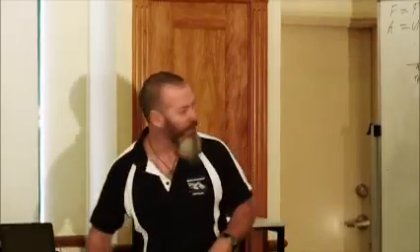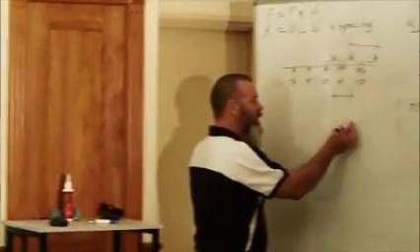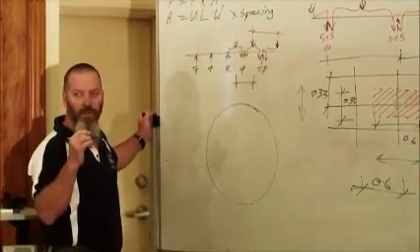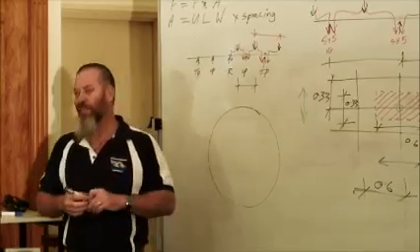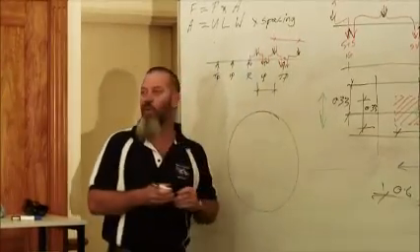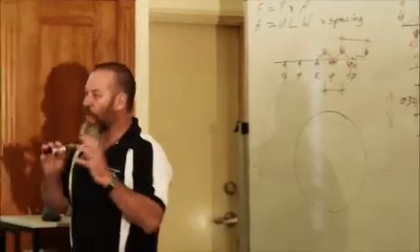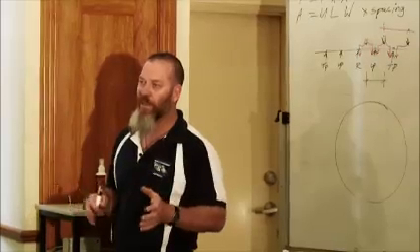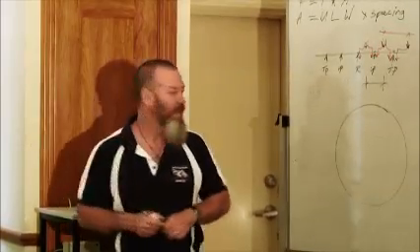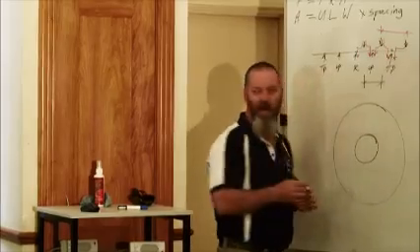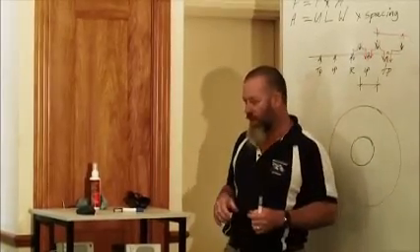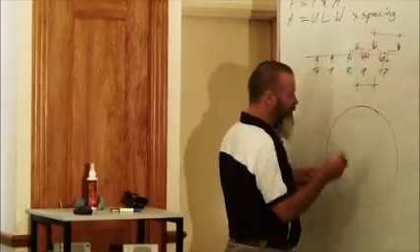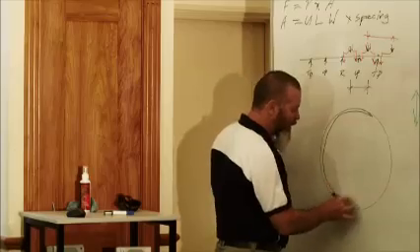Now the heart, by way of explanation, I'll tell you a little bit about trees. Treated hardwood is kind of a bit of a misnomer, because you can only treat the sapwood of a piece of timber. You can't treat the heartwood. Even in pine, it won't accept the treatment or it won't hold the treatment. Now a pine tree has a heart about that big proportionately. So it's only about 20% of the section size of the timber. But a piece of hardwood has a sapwood about that big.